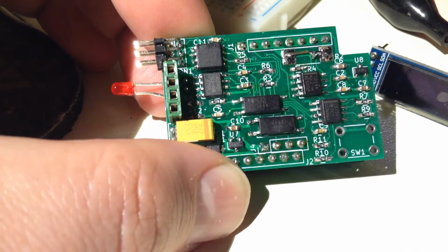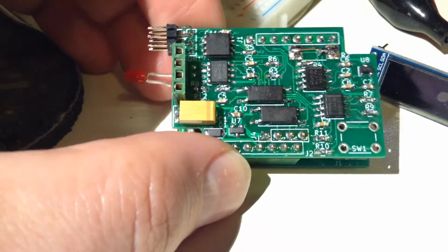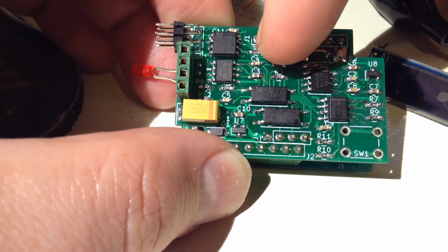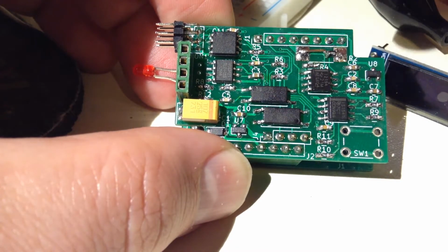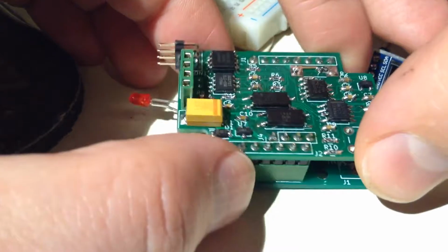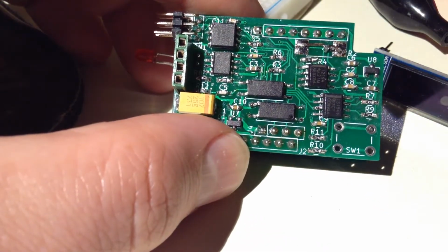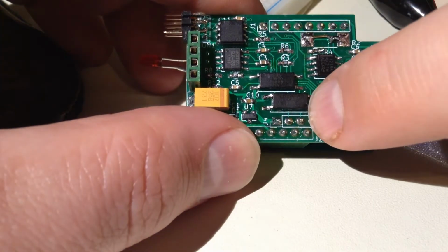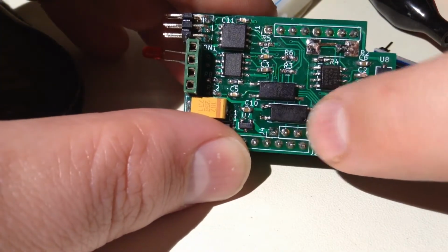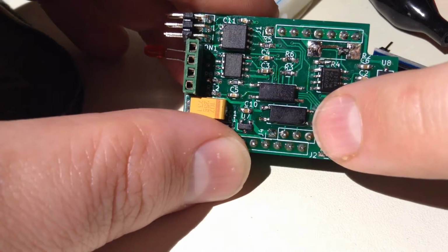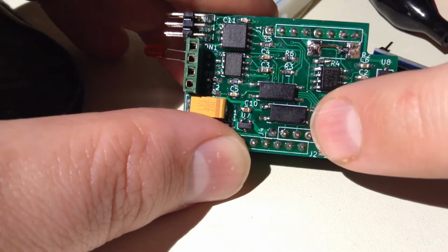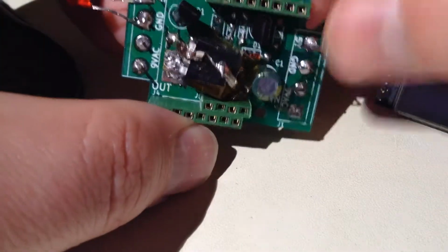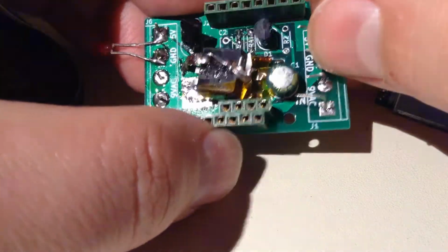The reason for that is because the board runs off of 9 volt AC, which is isolated from the 5 volt, and if I want to control the 5 volt section, I need to isolate. Also this one is reversed, you can see the notches here, and that is an indicator for the 5 volt part. Yeah, there you can see the Frankenstein circuit.